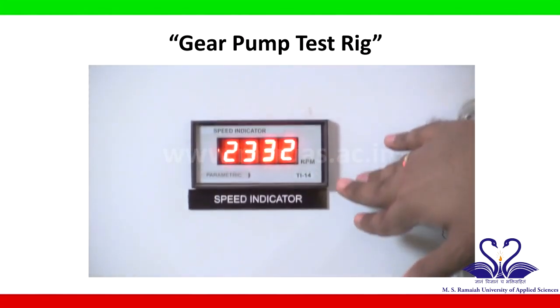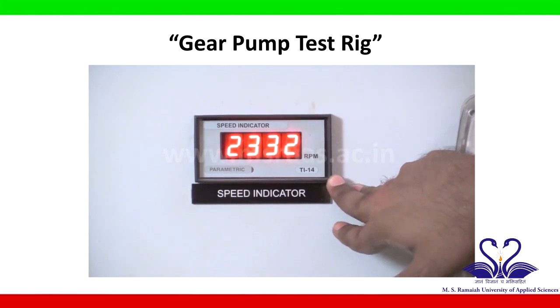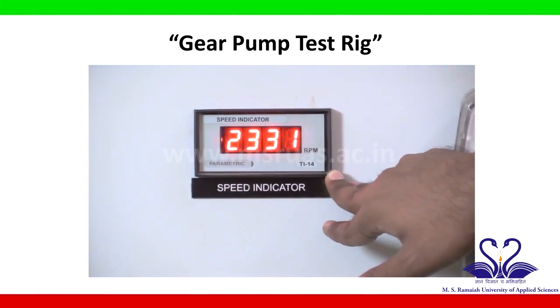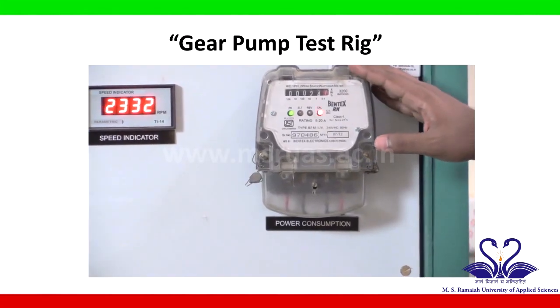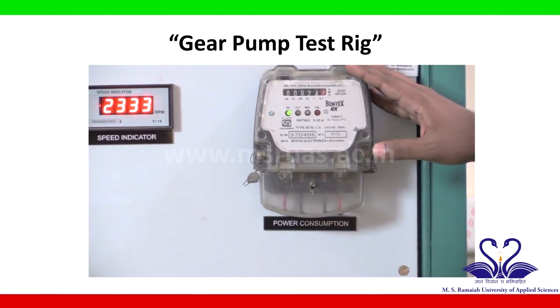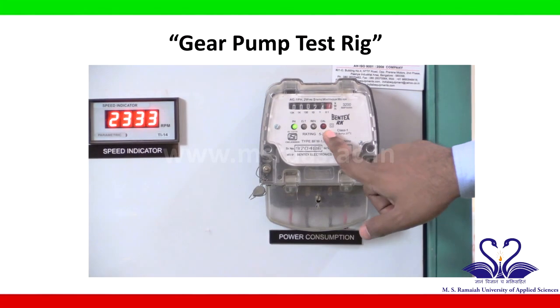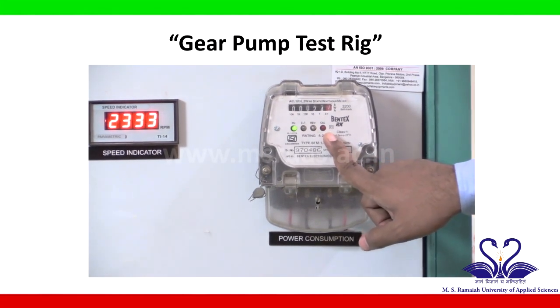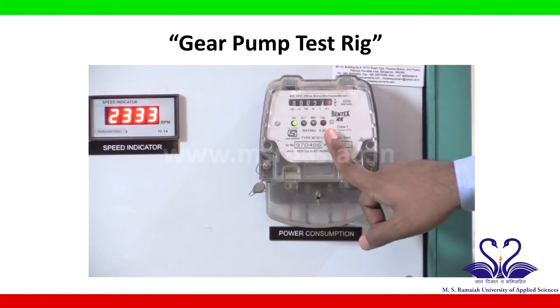The speed of the pump can be indicated over here, which is showing a speed of around 2330 rpm. The power consumption of the motor can be calculated using the energy meter. As we can see, there are a certain amount of blinks. So for that number of blinks, the time required has to be taken, and using that and the energy meter constant, we can calculate the power consumption of the electric motor.